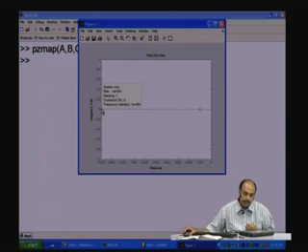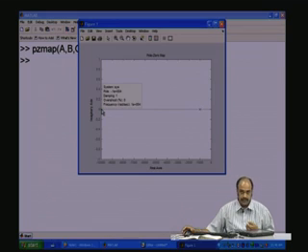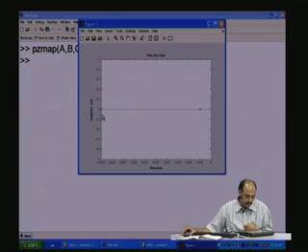So, this system, which has the frequency in radians per second as 10,000, as compared to this system which has a frequency in radians per second as 1000, will definitely be 10 times faster. That is what we saw in the time response, where with the 100 microfarads you saw the rise time of 2.5, and in the case of the changed parameter, where C1 was changed to 10 microfarads, you saw that the rise time was 0.25 milliseconds. So, there is the correlation.